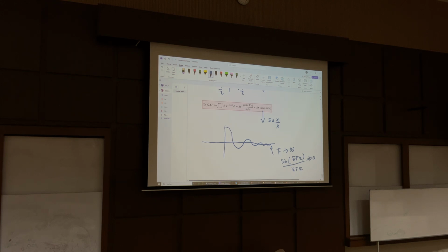So what we see is that this pulse contains, theoretically, all the frequencies, but the amplitude goes also to 0. That would mean from a certain frequency onwards, the amplitudes are meaningless. And that depends on the tau. If tau is very small, then the higher frequencies are present, because then pi f tau remains small.